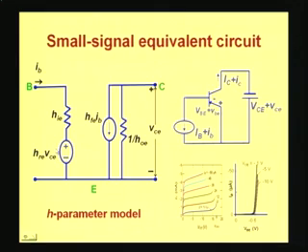that is the relation between this voltage and the collector to emitter voltage, the ratio is hre. So this is the small signal equivalent circuit as per the H parameter model. Generally, this voltage source which is present here is negligible, and so normally it is neglected. So the H parameter equivalent circuit used in practice has only three components: a resistance at the input, and a controlled current source in parallel with a resistance at the output.